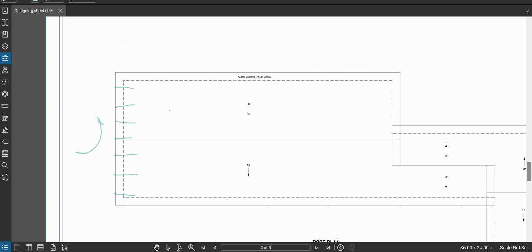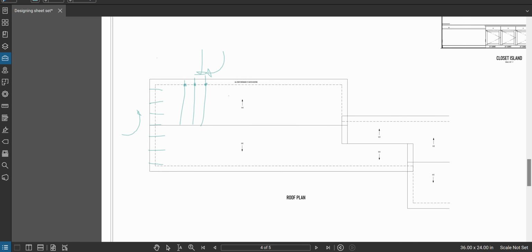And then hurricane ties: I'm concerned with the ends of my rafters, right? So I've got a rafter coming down, rafter coming down, rafter coming down. I want to make sure that the wind blowing in this direction, which is going to blow up the wall and try to rip the roof off, is not going to rip it off, because either I don't have enough wind to worry about it, or I have a hurricane tie here. So there are ways to check those things, and we're going to check for those. But that's going to conclude the calculations part. And we will do a few other